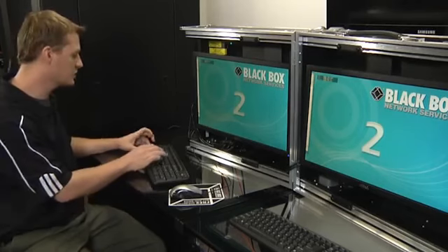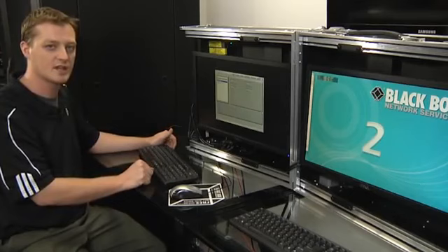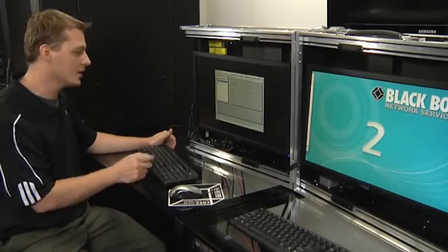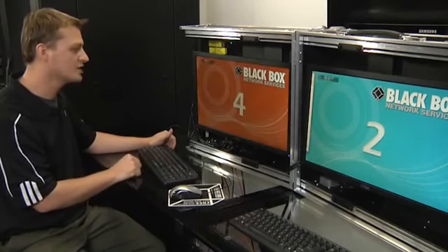If I prefer to switch via an OSD to get a list of computers or targets that I can access, I can use the hotkey Shift-Shift-O. Once I'm in the OSD, I can use my arrow keys, select the target, press enter, and connect instantly up to one of the targets or computers. If you prefer RS-232 or serial switching via the control card on the matrix switch, you can do that as well. So this covers the SurfSwitch Dkm Fx solution.